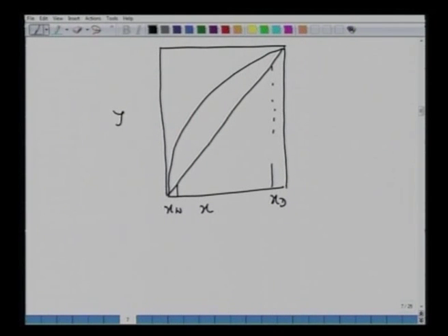So what we do here, let's assume that we know the reflux ratio from the total condenser. Let's assume it's the total condenser. So the vapor phase composition y1 is the same as xt, the same as what goes to the top plate as x0. All three are the same. Total condenser. We know the reflux ratio as L0 over D, or L over D. So with this xt, now we draw this operating line.